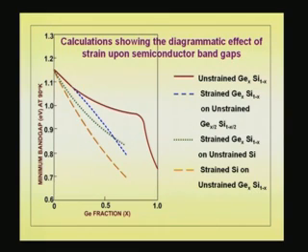So, you can see here, in fact that suits you. You can mix very small quantities of germanium and still get a band gap which is lower than that of silicon. See, the top curve here is unstrained silicon germanium. This particular curve is actually the strained silicon germanium on unstrained silicon. You take an N type silicon substrate, grow silicon germanium, that is a strained layer, then this is the band gap that they have estimated. Okay. So, you get a band gap which follows this rule, which is much smaller than that of unstrained silicon germanium.